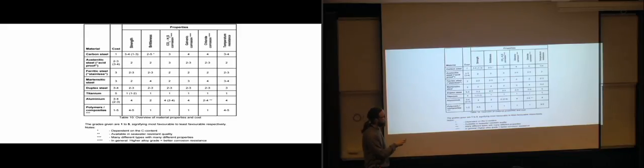So if we go down to polymers, very unfavorable with regards to strength. It's not really all that strong, but it's very favorable with regards to the corrosion. We could look at martensitic steel, very strong and also very favorable, and quite a lot cheaper than titanium. So it's sort of a way of doing a guesstimate of what kind of material would be useful to have in your particular situation.